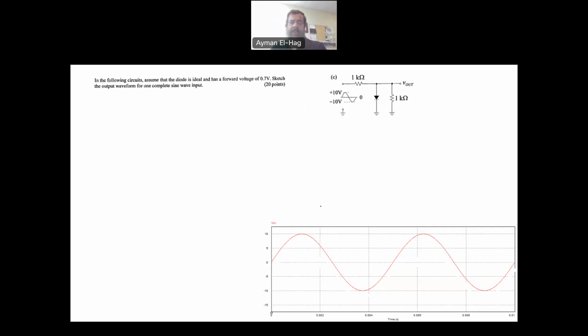Let's see the third question. In the third question here, if you remove the supply, the diode will not be conducting, because there is no DC supply here. Okay. So now let's see what will happen if I add the positive. When you add the positive polarity here, plus minus, the diode will be conducting only when the voltage exceeds the 0.7 volt. If it is less than 0.7 volt, your diode will be open circuit.